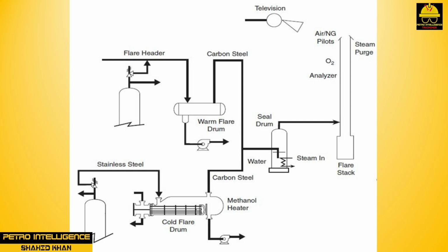A typical flare system includes a flare, a long, narrow pipe mounted vertically, a steam ring mounted at the top of the flare, used to dispense hydrocarbon vapors, an ignition source at the top of the flare, a fan mounted at the base of the flare, used for force-draft operation, a knockout drum with water seal, and a flare header.